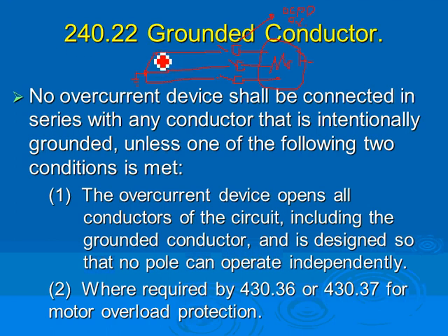What they take is they take this system and they run it into the panel. I'm going to run it from this side. Let's come from here, and here, and here. So what they do is they run these two hots into a circuit breaker, and this one runs into a ground bar. That's how they do them inside your panel. So really weird, and it caused a lot of trouble. So this will be the white conductor, imagine here, coming to a ground bar here, and then you have to ground this one in your service, bond it.